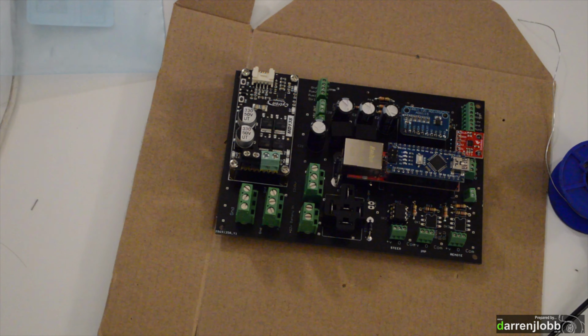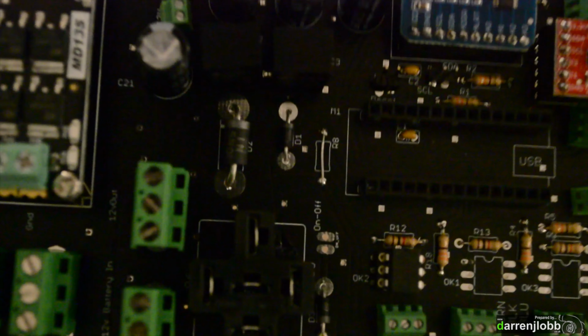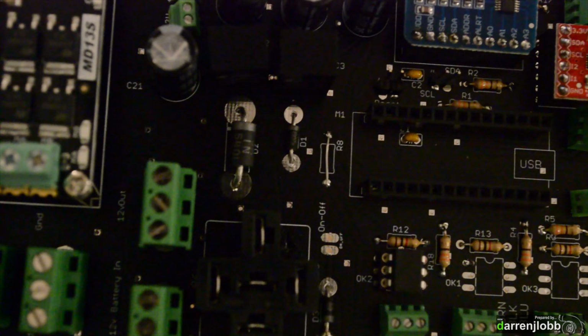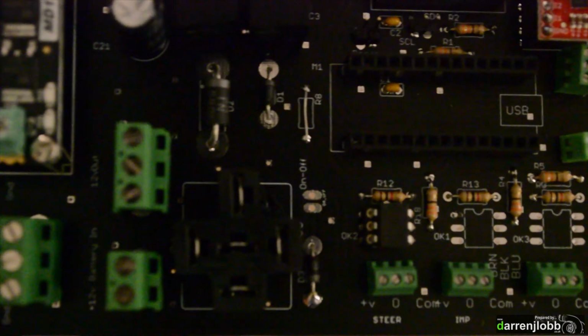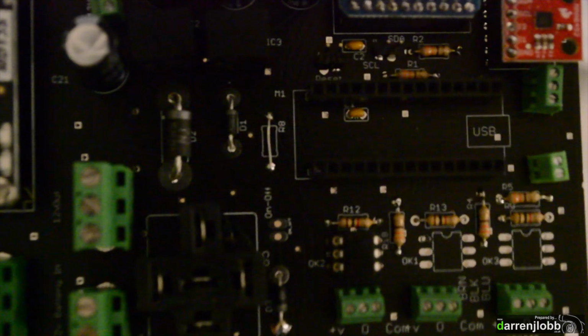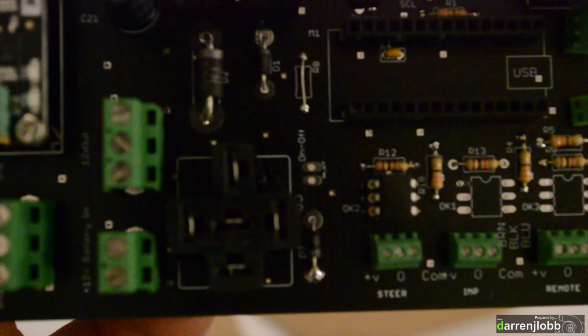I'll just slot a relay in there in a minute. Last little step here, we've got two marked points on the board, and it says on off. So this is basically where you wire in your power switch for the board. That basically triggers the relay to turn the whole system on and off. So it's up to you really what you do there. I see a lot of people have just soldered wires straight to the board. I think I'm actually going to solder a little block on there so I can attach and detach wires, but it really makes no odds what you do for that one.